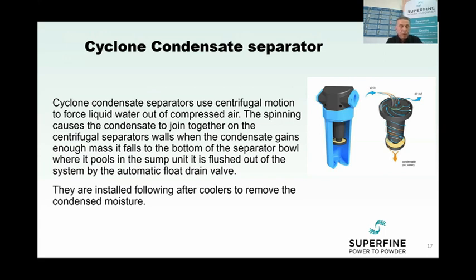The separator can also remove oil from the air. A mixture of compressed air and oil leaves the air end and is passed to the separator, where most of the oil is removed from the compressed air using directional and velocity changes. Then condensate filters are used to remove the remaining oil, resulting in very low oil carryover, usually between 2 to 5 ppm. This means that air from this separator will have less oil than a regular one.